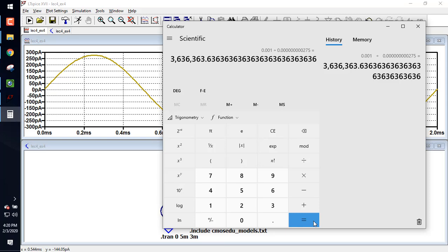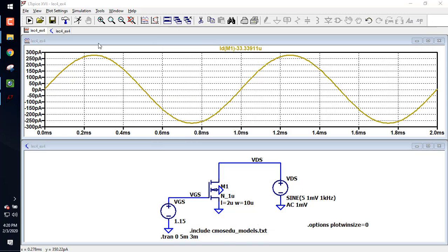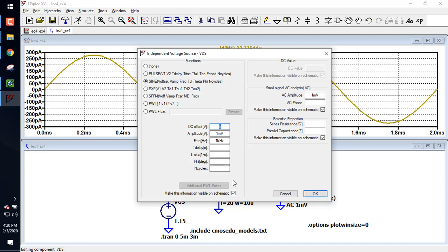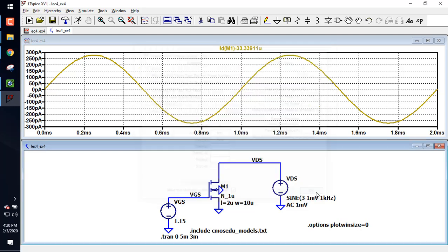That problem was hard. I'm going to finish the hand calculations, but before I do, does everybody see that that's 3.6 meg and it's like 5 times different than what I calculated? Okay, I'm going to save it, and I'm going to show you something, and we'll talk way more about this later. I'm going to have to change the DC offset, but that's fine. I'm going to change this to 3 volts. It shouldn't affect anything, I'm still in saturation. I should get the same exact AC current.